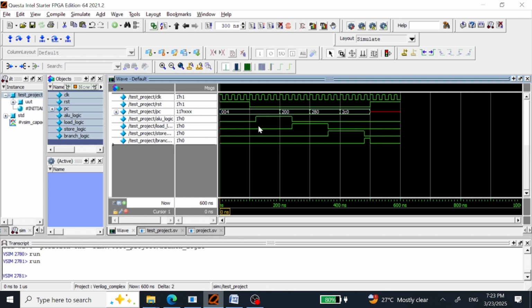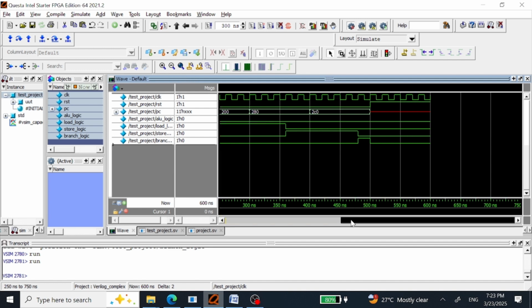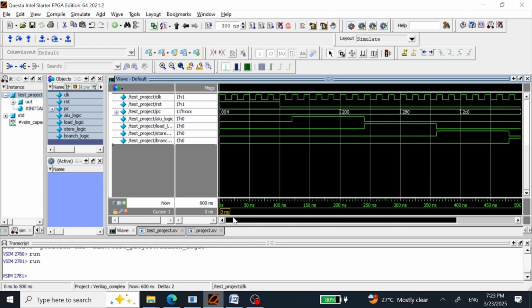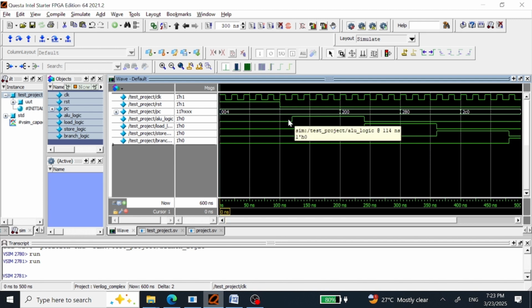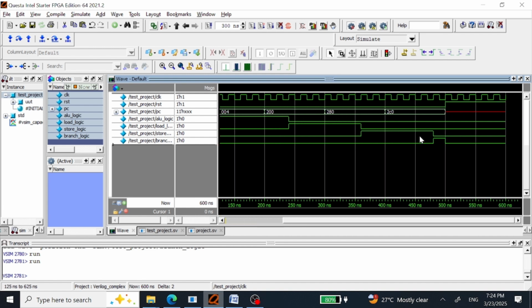So you can see the difference here in the waveforms already. Once we use the wait statement, see how it is delaying the signal. Here is a 1 clock cycle delay, and here it is even extending the signal by 2 clock cycles, so the period here is bigger. Here it is getting delayed by 2 clock cycles. Here it is getting delayed until 3 clock cycles, and here it is getting delayed by 4 clock cycles. So this is the difference.